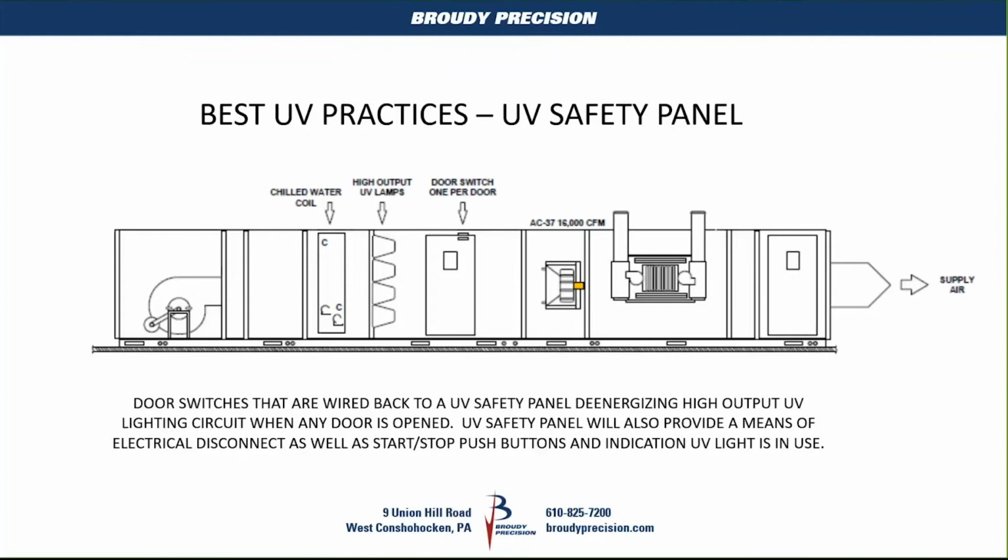This is Ron from SDA. I have a question. When you talked about sensitivity to skin and eyes causing cataracts, that's obviously only if you're exposed to the actual UV light, correct? That is correct. That's why these safety panels that we make, as soon as the doors open, it opens the circuit for the lighting and turns the UV lights off. So the safety of the technician or the maintenance individual working inside the chamber is never compromised.